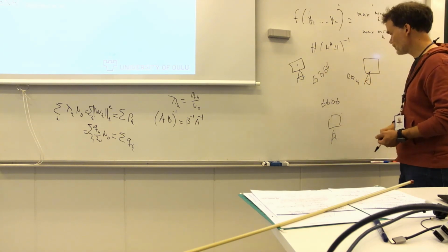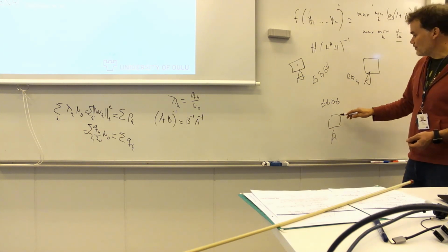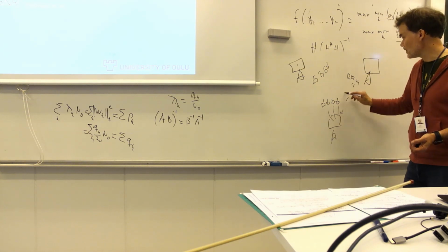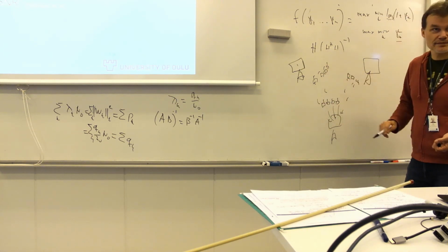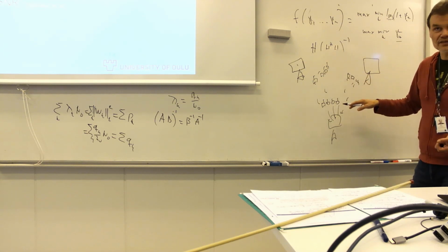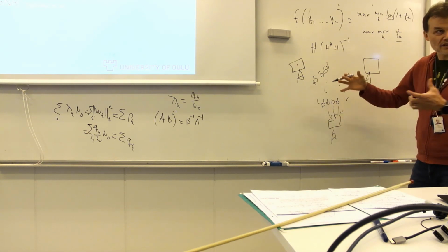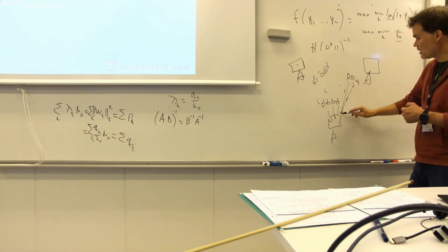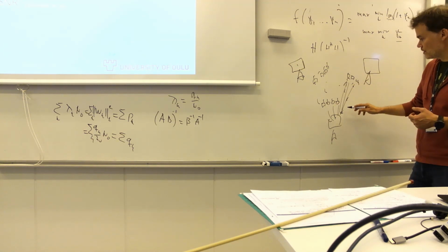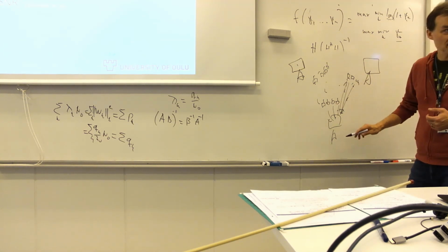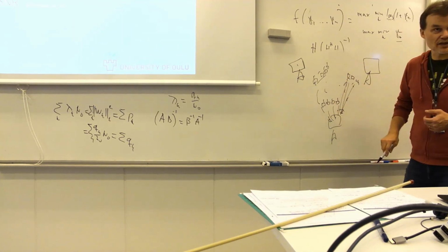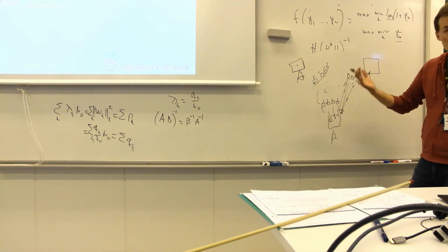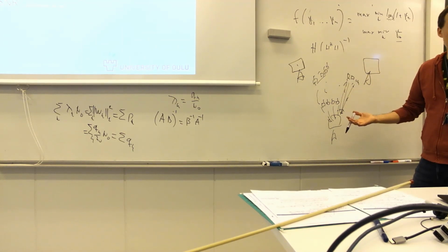This one here is also serving 4 users. But now, if we just design the beamformers based on a single cell, we are ignoring the interference. And this interference can be significant if the users are close to the cell edge, for example. So we have to also assign some dimensions. Basically, in the inverse, you should also take these channels and these channels into account. And now, if you want to have a zero forcing solution, the null space is 1 again, right?